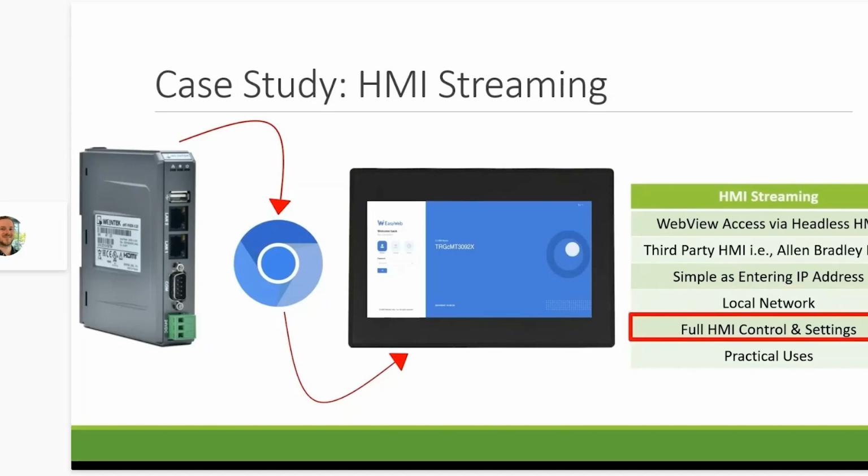The web HMI does not just broadcast and display the main HMI it is connecting to via the web either. It allows full access and control of the HMI project as though the web HMI has the same project downloaded to it. However, nothing is actually downloaded to it since again it is a client-based unit. This means that you can have several web HMIs across your facility to help better integrate and ease of access for operators.